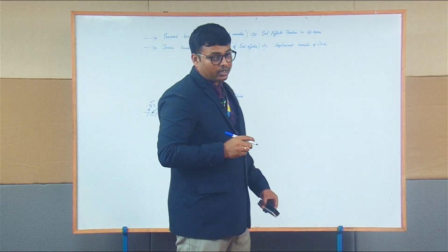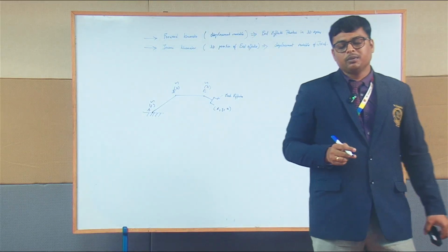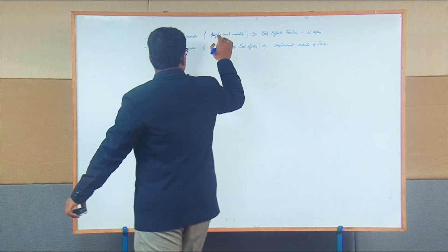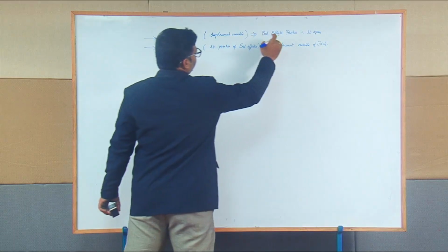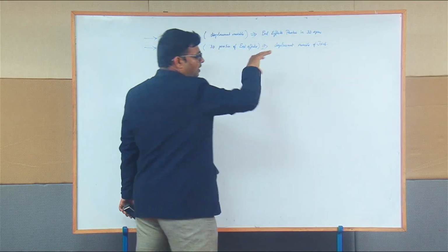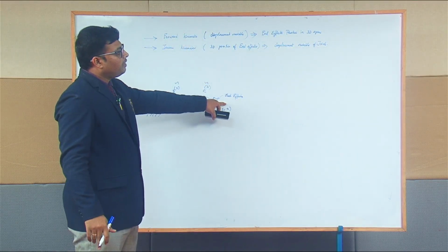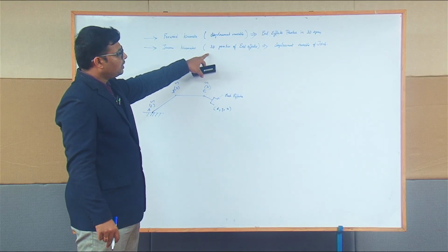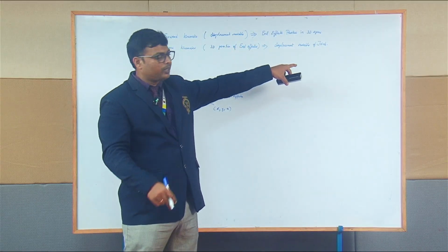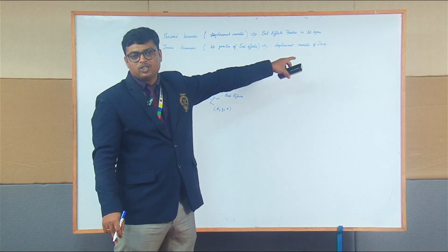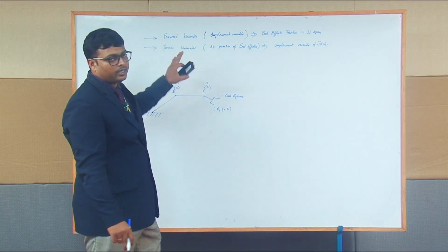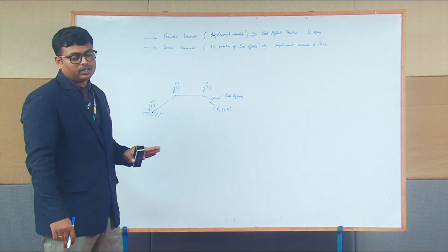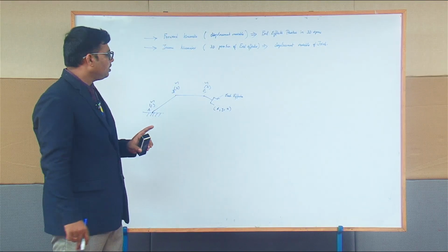So this is all your understanding about the motion behind robotics in industrial robots. If I know the displacement variables, I am able to compute the position where the end effector is located. We call it forward kinematics. Knowing the end effector's position, if I am able to recompute the displacement variables in the joints, then it is called inverse kinematics. So this is all about the study of motion with respect to industrial robots.